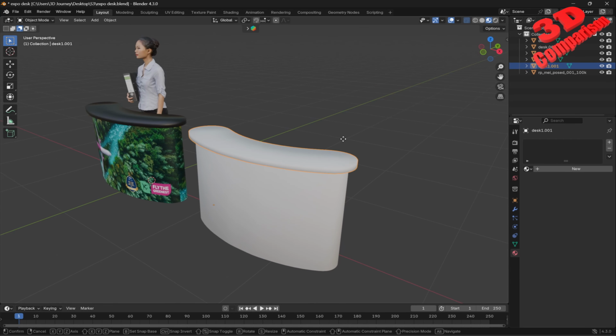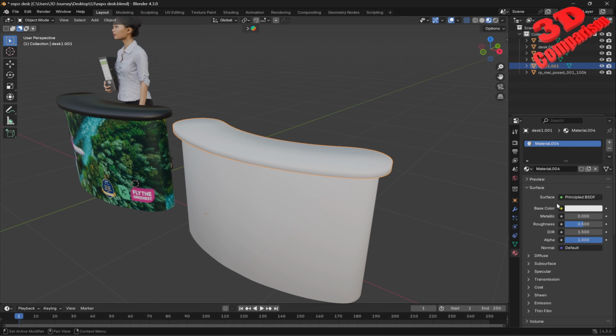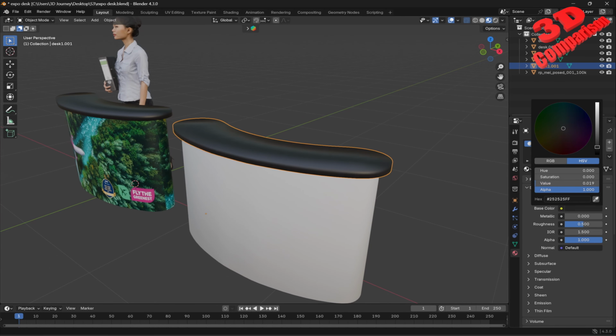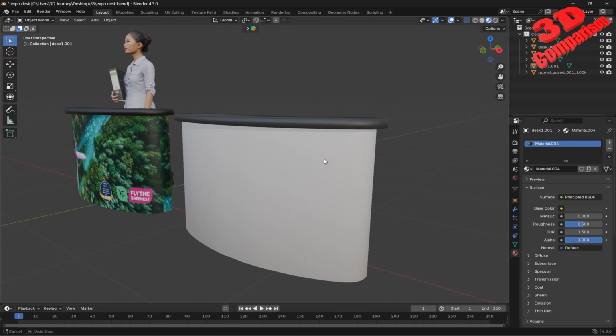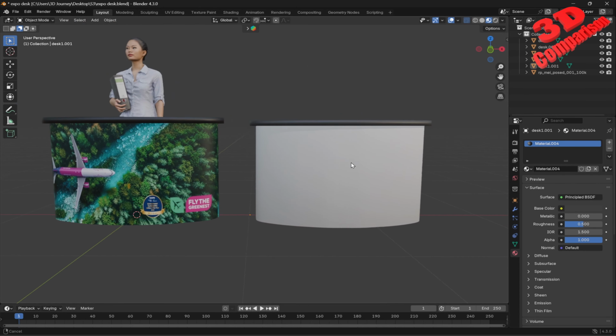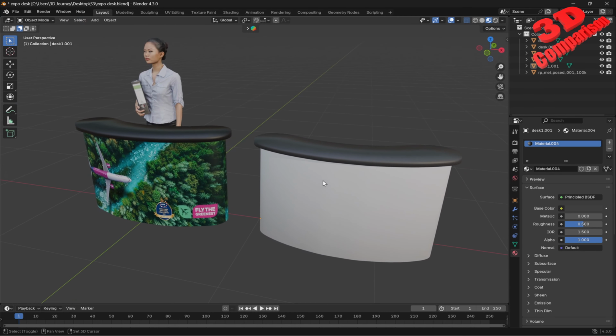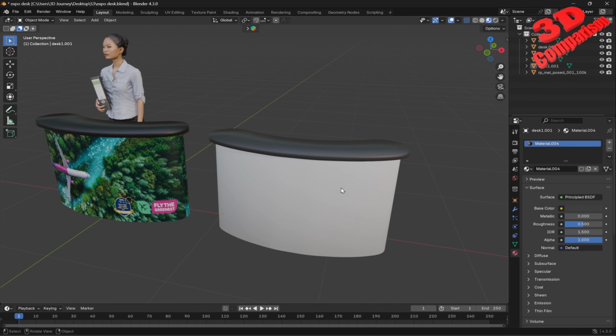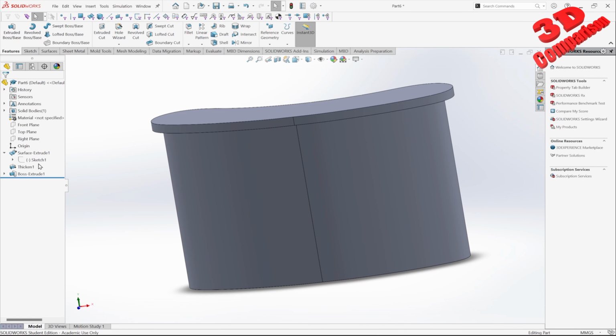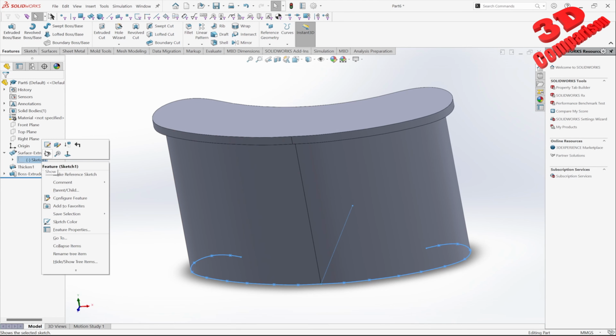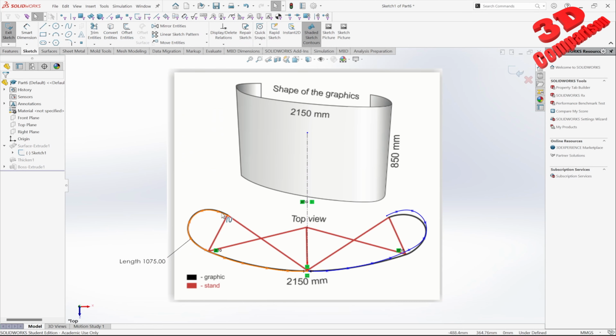And now I can just select the top part of the desk and I can have that individually transferred and manipulated. So I can just adjust the color of that desk, and afterwards we can start with the banner on the bottom. But that will be within a following video. So this was mainly regarding SolidWorks and how we can trace an image. So we see it over here, and the most important thing is that we can use the length of the spline in order to calibrate images in this case.